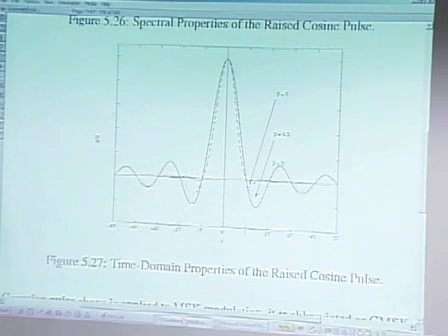What you do is, the answer has two parts. First, you actually truncate this. Even though these tails go on forever, they get truncated. Usually the symbols are synthesized to have a duration of about 6T, I would say. So usually you just cut it off around -5T, -6T on each side. That's the first part of the answer. The second part is what happens with the anti-causal part. Let me defer that for a second and complete the first part of the answer.